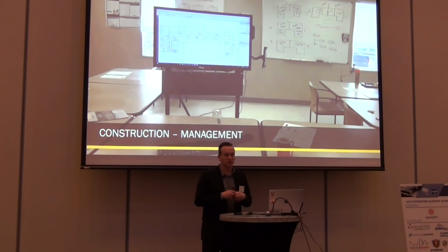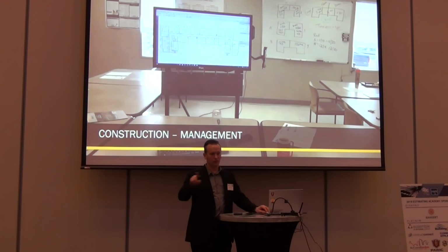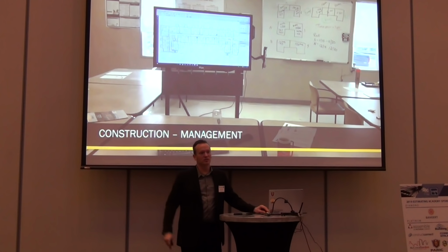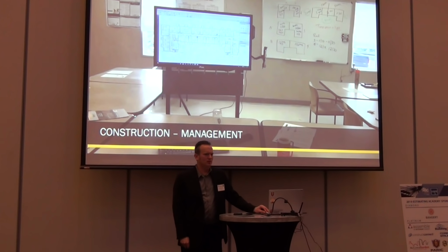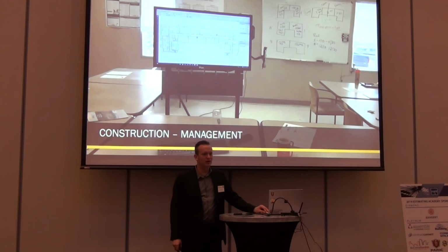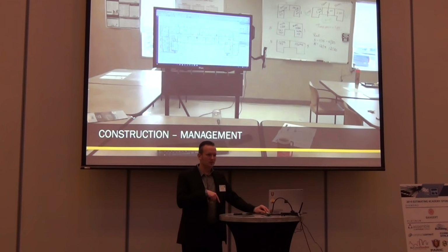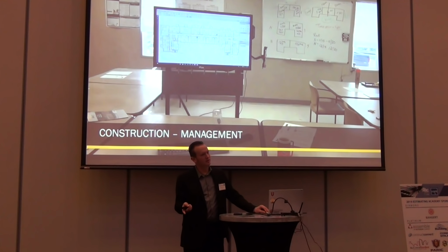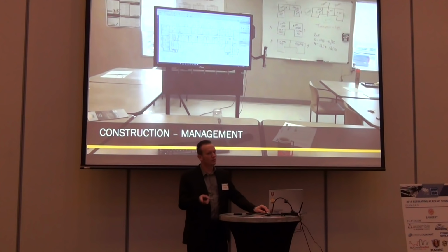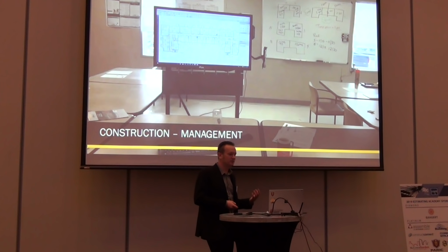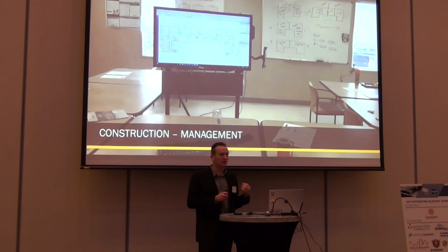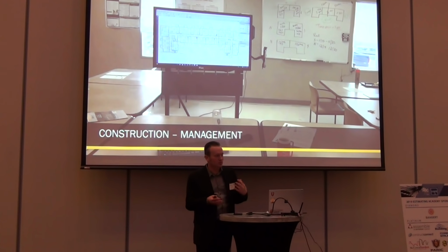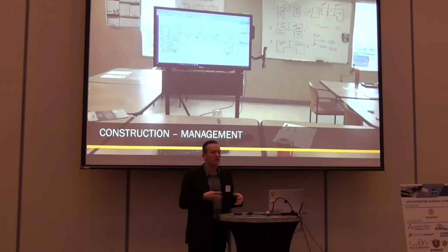If I estimate just based on quantity, I'm going to give it a quick little formula and say, all right, I'm going to use this many forms across this entire project. But I'm not going to pour 1 million square feet in one day. So I can reuse those forms. So do I modify my formula, or do I modify the model? There's all different ways to go after this. So the way that you set up that estimating database is going to be largely based on how well your team can work together and how well you can strategize on how to model and how to do the takeoff.